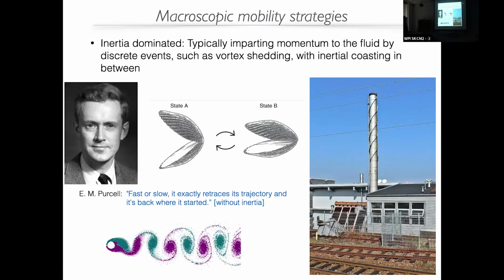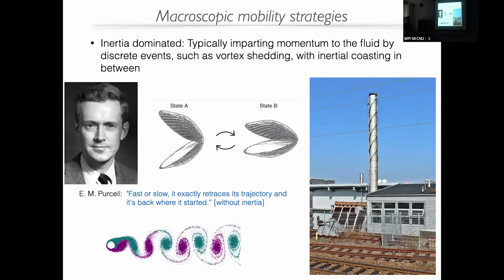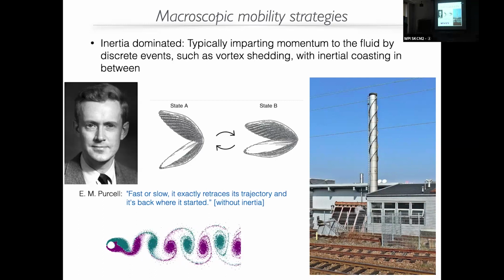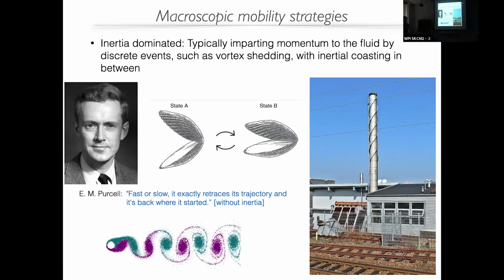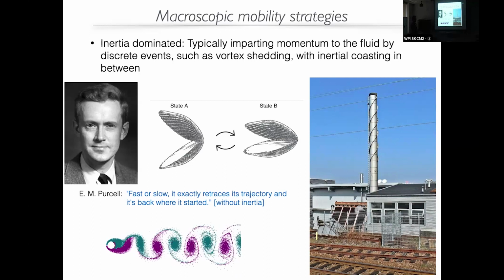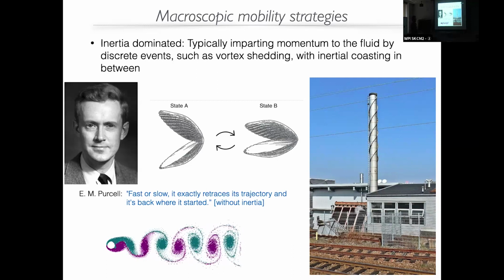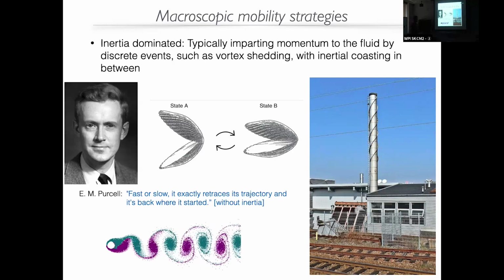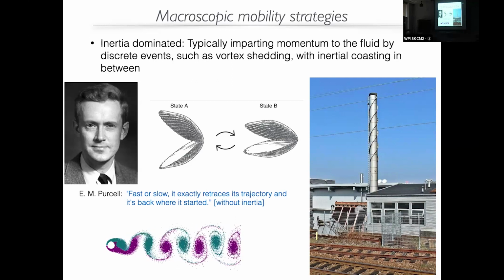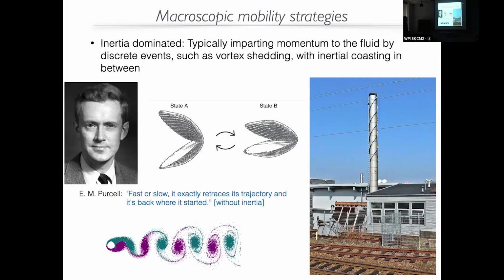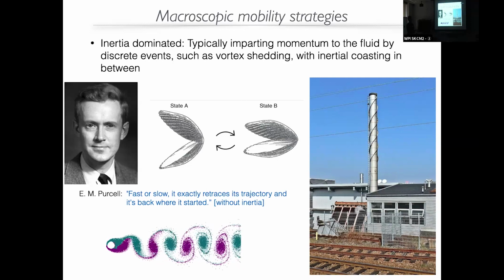Vortex shedding has to do with fast fluid motion relative to objects which are not streamlined. So this is not your typical Shinkansen train. This is more like an object like a sphere or a circle that's not very well streamlined. Fast enough hydrodynamic flow relative to such non-streamlined objects, at some critical velocity, starts producing a sequence of vortices emanating in the wake of its motion.